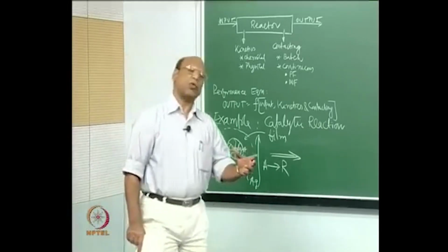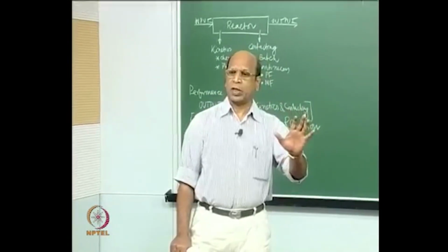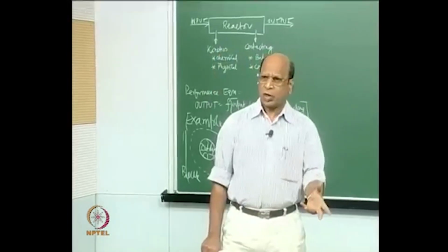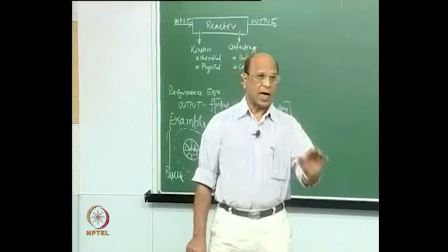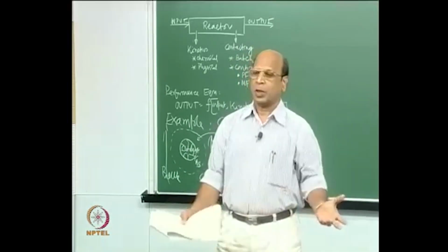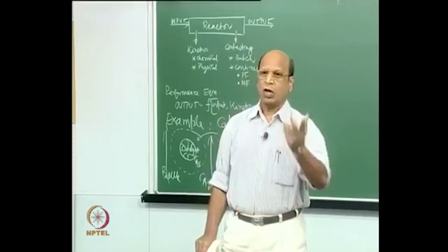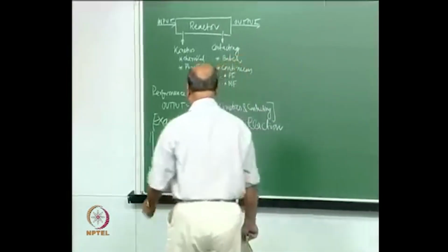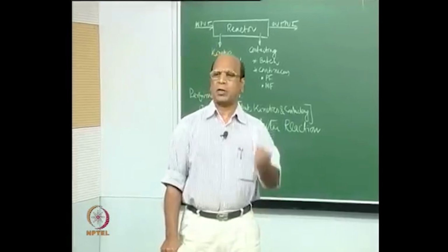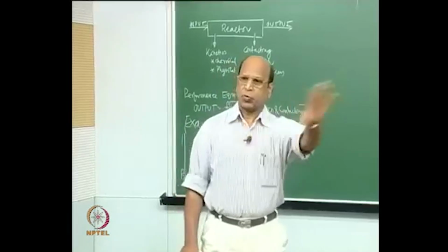Now, as an engineer, you can try to simplify many things, like for example, I will assume that I do not have a porous particle. What are the steps that will not be there? Adsorption, desorption will not be there. Diffusion of the reactants into the pore, and also product coming out of the pore is absent. Adsorption, desorption will definitely be there, but now it will be limited to the outside surface. That is one assumption. As an engineer, I can always try that, because my mathematics are going to be very complicated. Okay, let me try porous particle, non-porous particle, right. So, out of 7 steps, now 2 steps we knocked out.